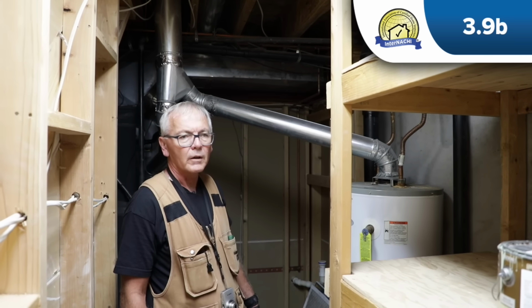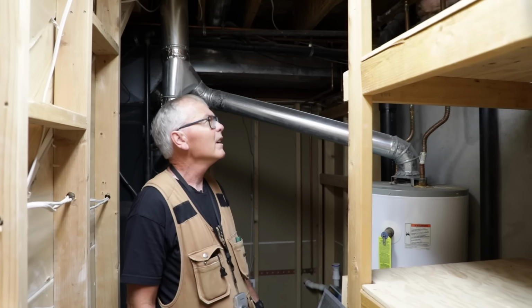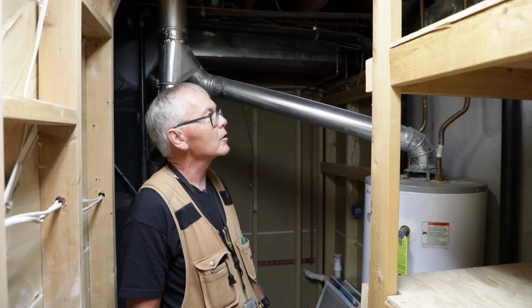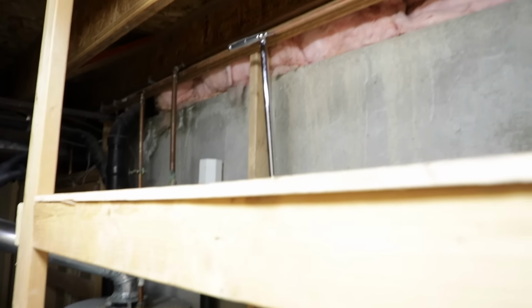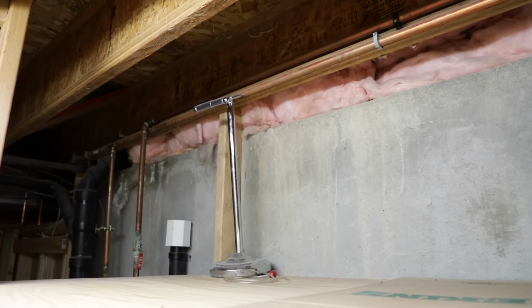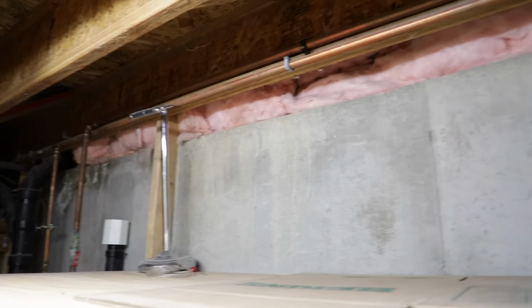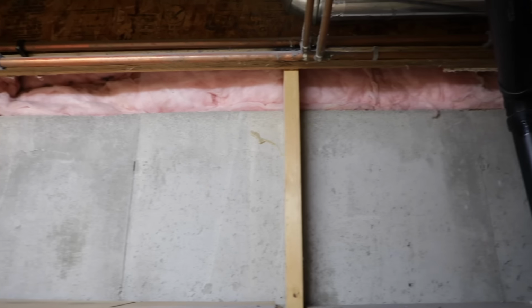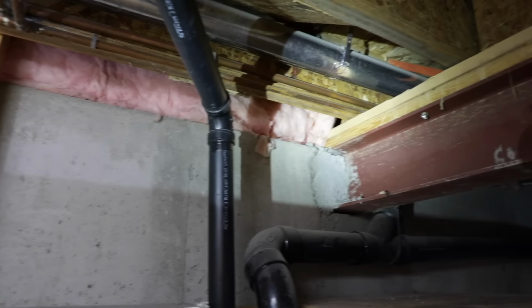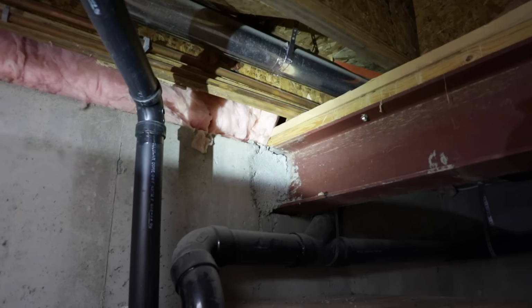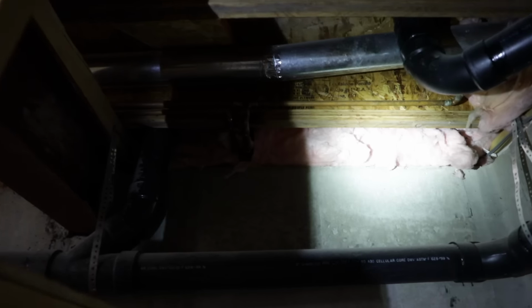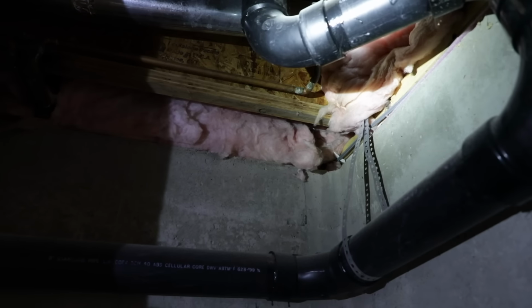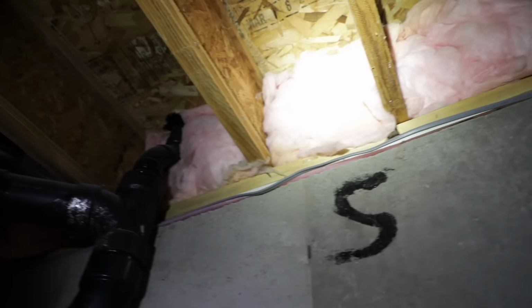We're down here in the unfinished room in the basement, and we're going to be inspecting the insulation in unfinished spaces. So the only insulation that we've got down here is going to be the insulation that insulates the rim joist around the outside wall. So we just want to look at that and make sure that we don't have any open gaps where cold air could come in. That all looks good there. We got a little bit more back here. Everything seems to be in place for this room, so that should conclude our insulation in unfinished spaces.